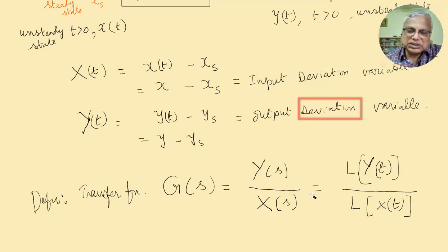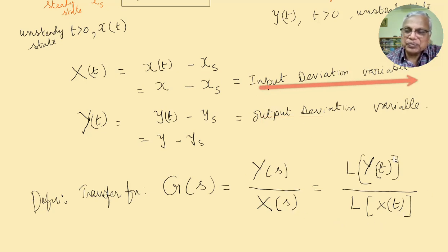So let me rephrase the definition. The definition of the transfer function is the ratio of the Laplace transform of the output deviation variable to the Laplace transform of the input deviation variable.